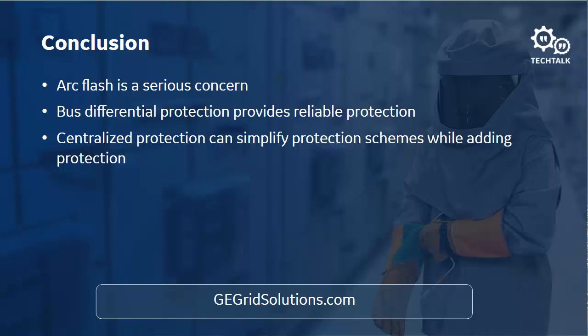It says you only talked about the bus faults. Can a feeder fault near the bus affect the equipment? So a feeder fault has the possibility of saturating your CT, and so it's going to require the differential to detect that or account for that so that it does not misoperate. The main circuit breaker for that one should be taking care of the fault on the feeder breaker.